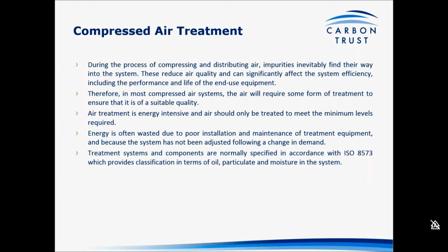The treatment of it is energy intensive. It shouldn't be overlooked, and as a result, you should only be treating the air to the minimum level required. So say you're running a compressor in a garage for hand tools, you're not going to have to treat that to any great degree, but where you have compressed air operating machinery in a food manufacturing facility, then the treatment of that air obviously has to be to a much higher standard.